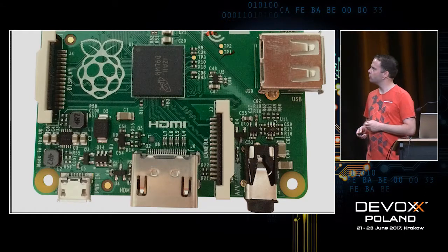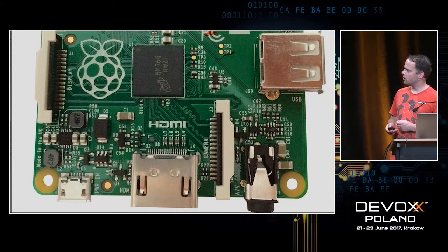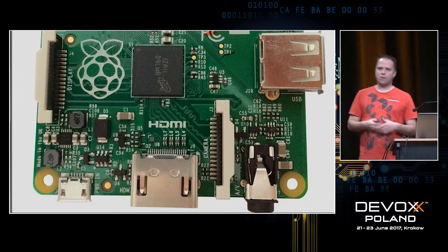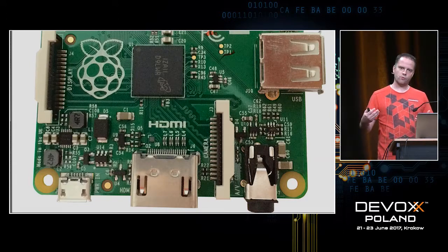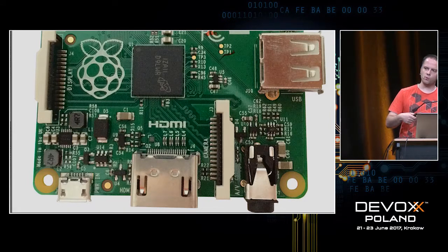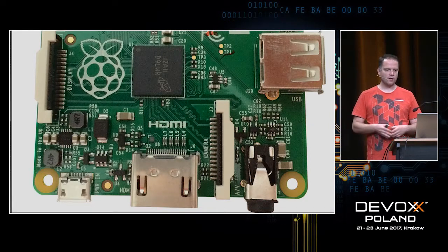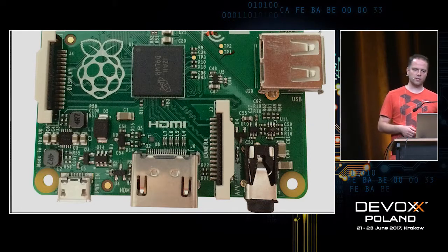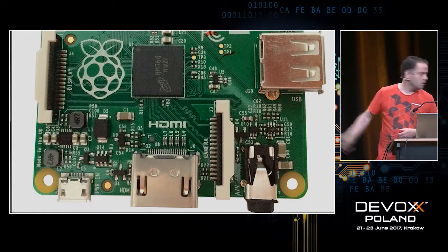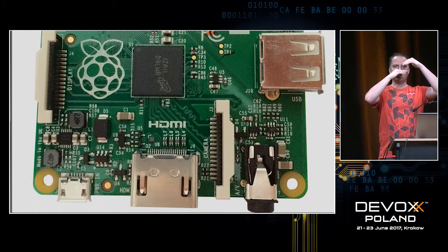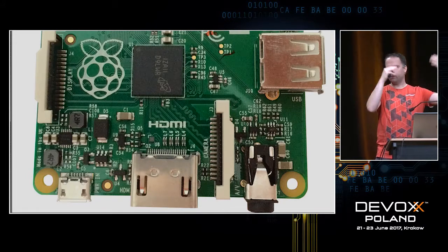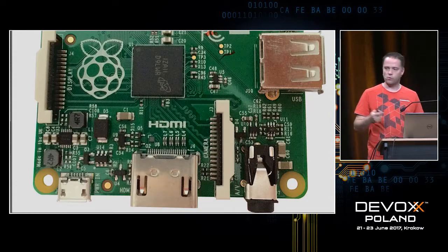So it's quite okay from a resource perspective. One thing to keep in mind is if you start using the Raspberry Pi A+, be really careful with the USB connector. I bought 3 of them, tried the first one, didn't work, tried the second one, didn't work, tried the third one, it was working. And then, like I did with the first 2 ones, I inserted the USB Wi-Fi dongle and it stopped working. I took out the USB Wi-Fi dongle and I noticed that the pins, which you can see over here and over there, normally they keep the connector like this. But now they were bent backwards like this and basically short-circuited my Raspberry Pi, which was the end of my Raspberry Pi.